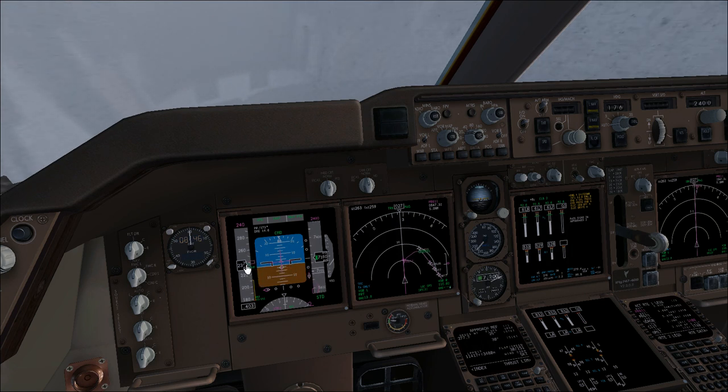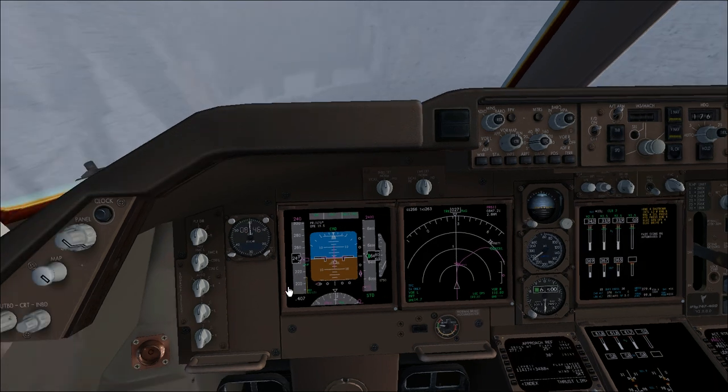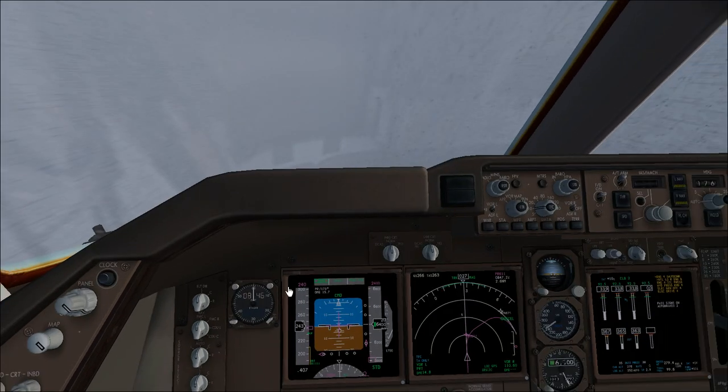If you stay on the desired speed for more than some seconds, it changes again to hold to keep the VNAV path plan for the arrival. As you can see, we are on the path completely and perfectly. We are now decreasing the zoom to show you the arrival. This is the point where the FMS commands the flaps up speed, and then every time you select a new flap selection, it will go to the next flap placard speed, and you will see in a few seconds what it means.